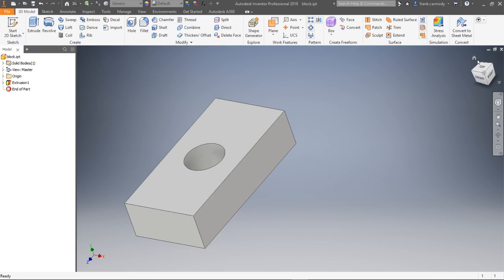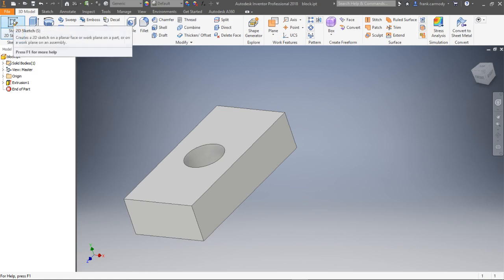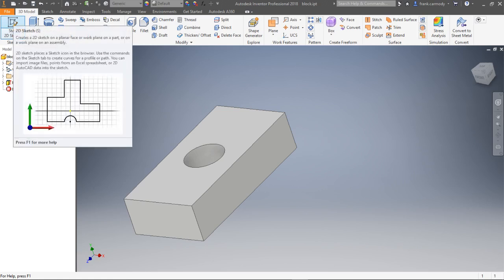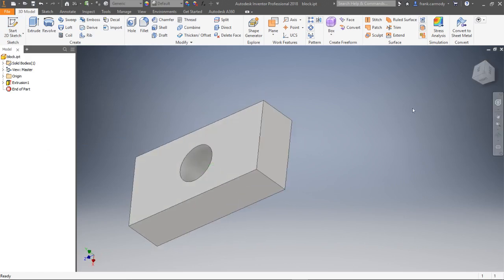So I just make one key. Now, obviously on a lot of keyboards, all the keys aren't identical, but some are, right? So basically I'd make one IPT and I'd duplicate it for all the identical keys. But let's say we do want to make something a little bit more complicated on here, all right? For example, let's say we want to put another hole in some other side of the cube, all right? Well, what we would do in that case is start a second sketch in the IPT. And that sketch can live anywhere on any one of these surfaces, all right?